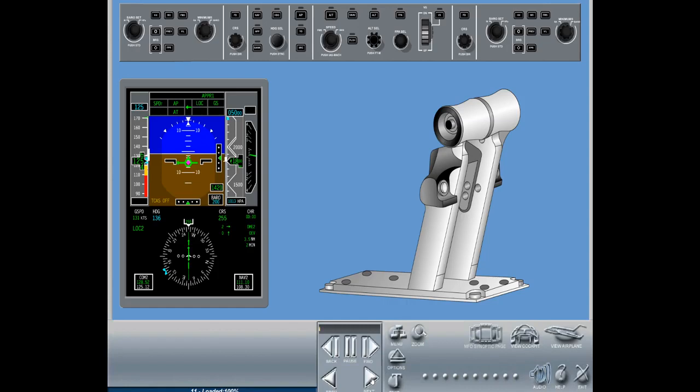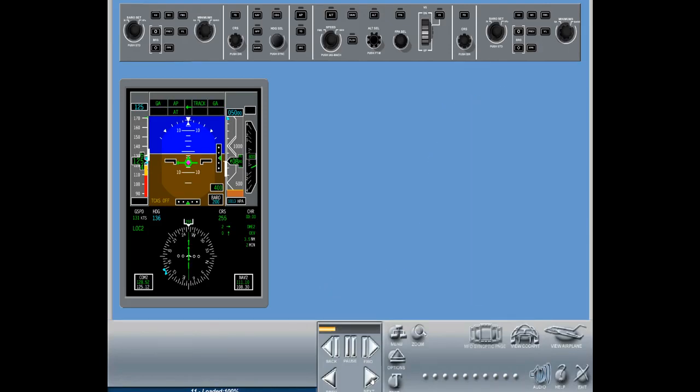Go Around, GA. The Go Around mode automatically provides Go Around guidance and thrust by pressing the Takeoff Go Around switch. The flight path angle and flight director symbols are displayed when the Go Around mode is activated. The Go Around mode initial guidance determines pitch at 8 degrees.